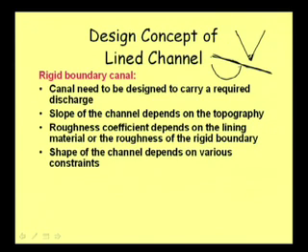Say we are trying to construct in a very interior place, and the framework required for constructing a circular canal may not be available there, and the labor available may not have that expertise to make a circular canal. So, there may be different situations which force us to take a particular shape.